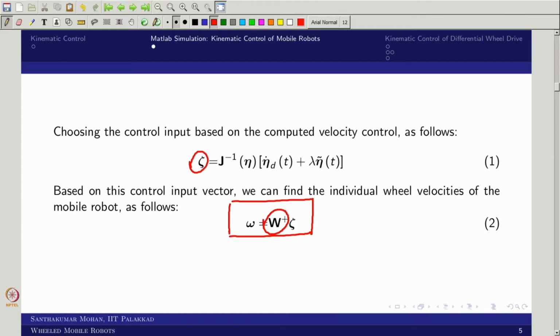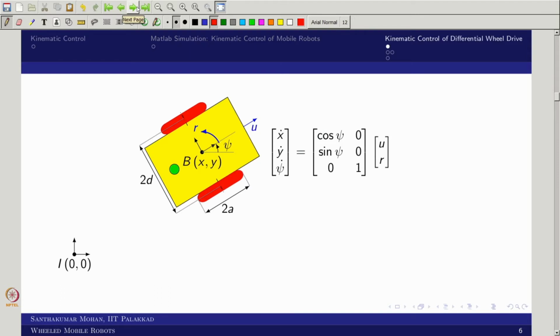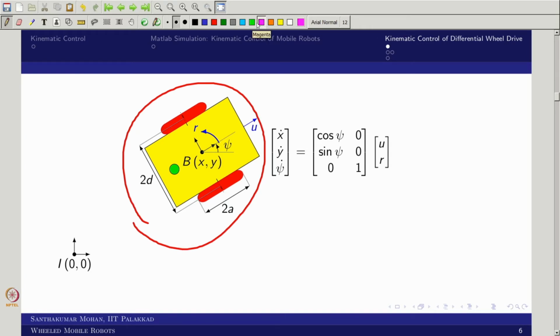Let us move to the slide and try to see. For the non-holonomic case, we have taken a differential wheel drive, which is one of the models we usually consider for all analysis. So this is x dot, y dot and psi dot. If you substitute v also, you will get something. But right now, in the final equation, since the lateral resistance is infinite, you can see that v no longer exists. In the sense, one can see only 2 states can be controlled.